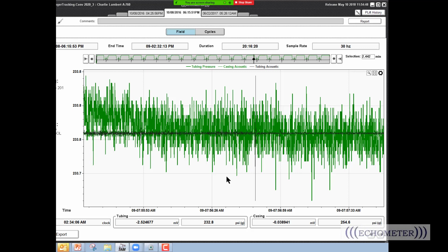When we had classes probably 5 years ago, if someone said, can you find the washed out gas lift valve, we would have said no, because there's no hole there. It's just a gas lift valve. But if you shoot the gas gun on one side of the casing or the tubing side of the well and listen with another gas gun microphone on the other side, the washed out valves will pass the signal through.